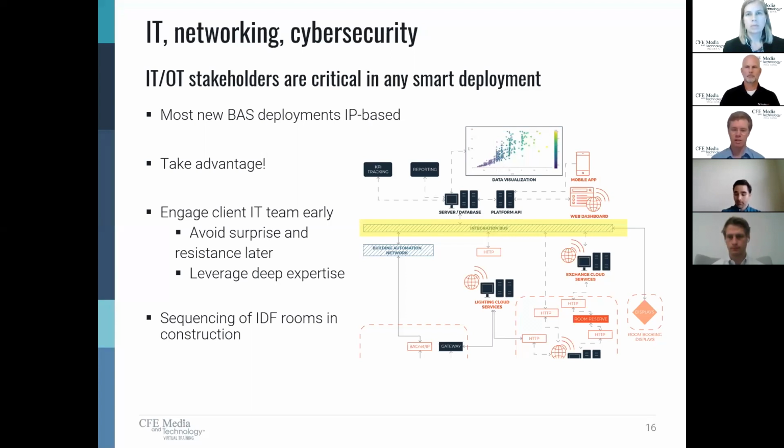And then of course the other, more technical point there, sequencing the IDF rooms or the IT rooms in any project, when those rooms are ready to be live during construction, during any new build or even any renovation or retrofit. Whenever you're relying on that IT network to plug in your systems, your sensors, that room has to be live and it has to be ready to go when they need to start commissioning the system, right? So that's a little earlier than we've traditionally seen.